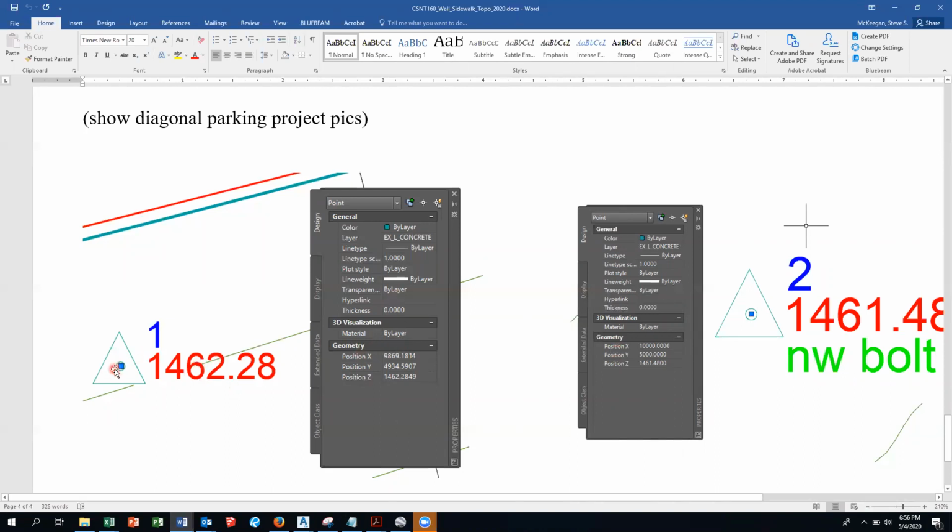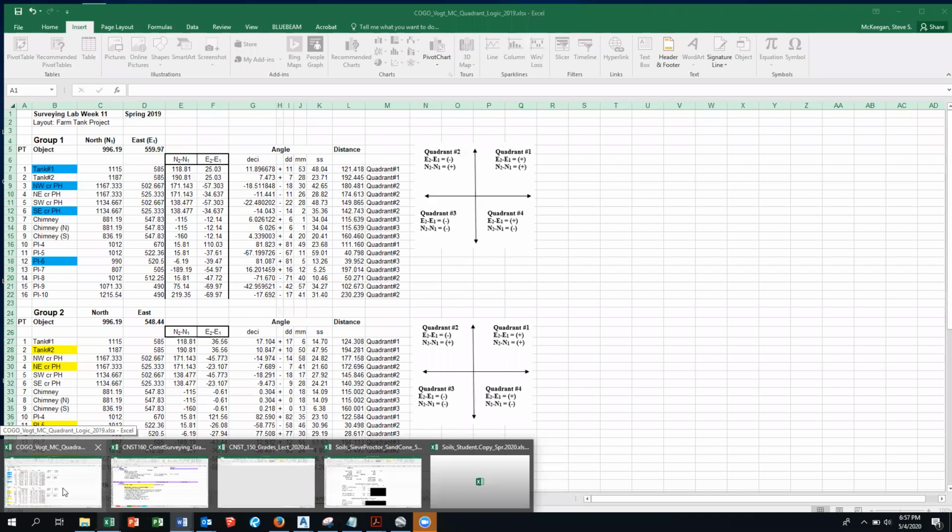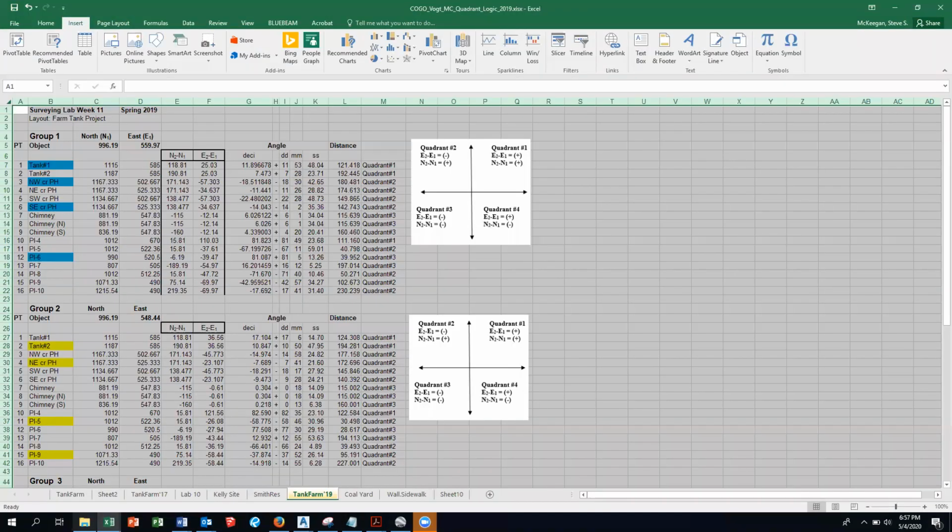if we're set up on delta 1, there is its northing and easting, and we shoot over to delta 2, and we know that northing and easting, that should give us the distance between the two and the angle off of either looking north for the back sight or looking south for the back sight. So you want to get familiar, and we've gone over this, you want to look through the PowerPoint for the Smith Hall layout, the garage layout, that will help you with the angles.